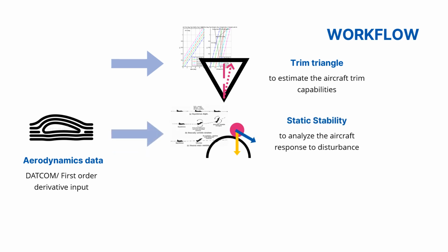Next, the program can trim the aircraft for steady, symmetric level flight using the known cruise airspeed or angle of attack, considering the specified atmospheric conditions. This allows users to trim the aircraft around a defined fixed point, obtaining the aircraft state space. With this state space model, users can delve into the dynamic stability analysis, observing the aircraft dynamics over time.